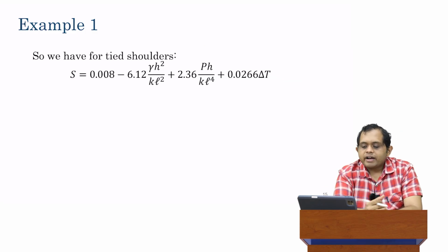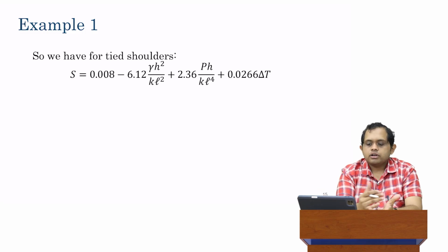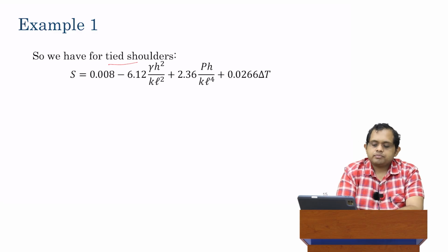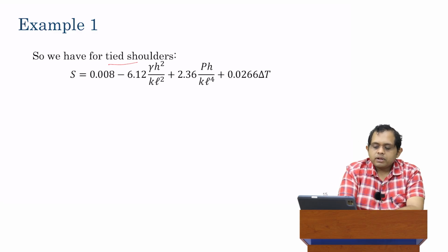Okay. So finally, here is our formula in all its glory. For this particular condition, for tight shoulders, for a K value which is less than 80 megapascals per meter, for bottom-up cracking, under those peculiar conditions for single axles, single rear axle, this is the equation that we have. Let's start plugging in our formulas, and here again be very, very mindful of the units.